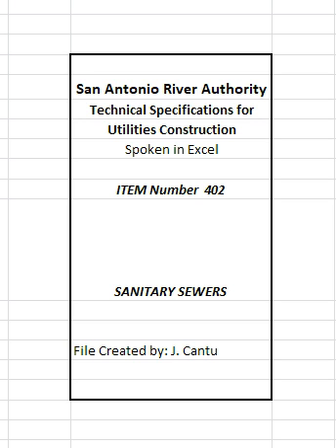When the depth of cover over the top of the pipe is 0 feet to 14 feet, polyvinyl chloride, PVC, sewer pipe and fittings shall conform to SDR26 ASTM D3034, 8-15, SDR35 ASTM F679 Type T1 wall, 18-27, ASTM F789 Type T1 wall with a minimum pipe stiffness of 46 psi.